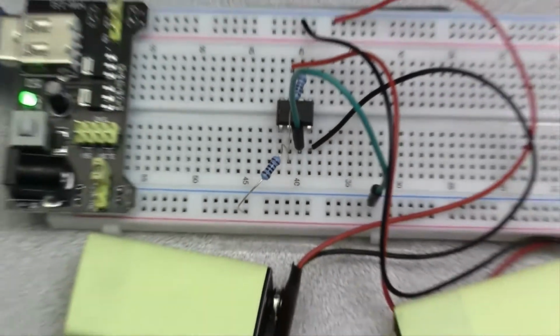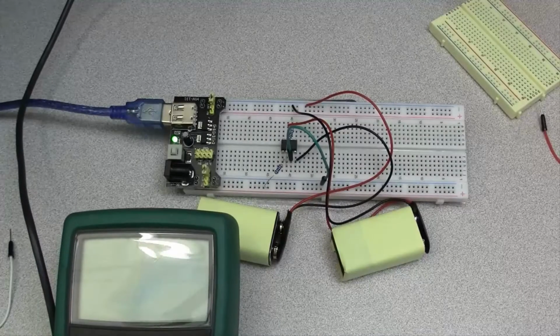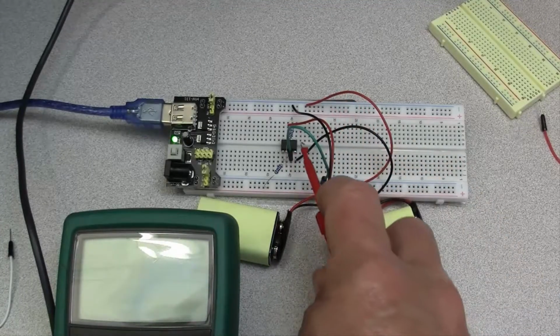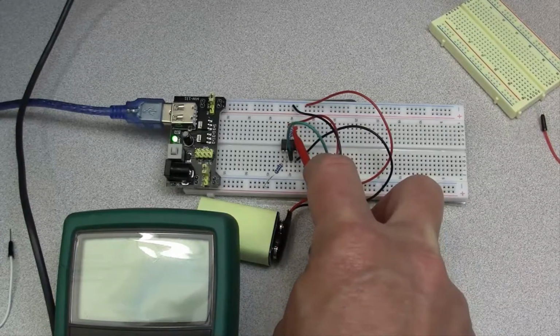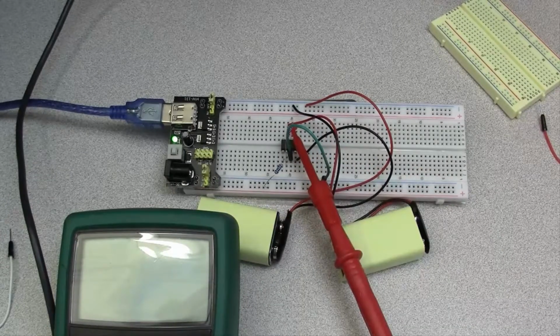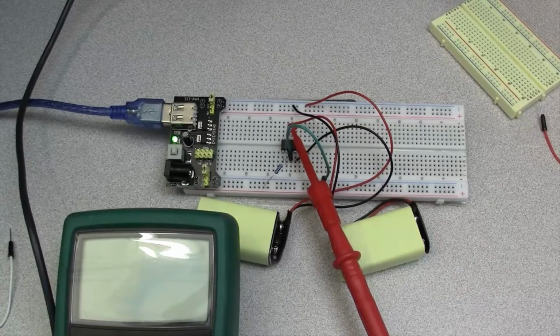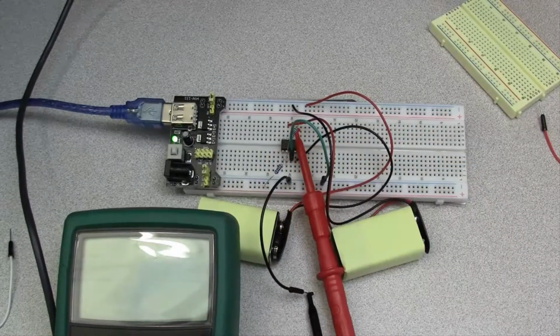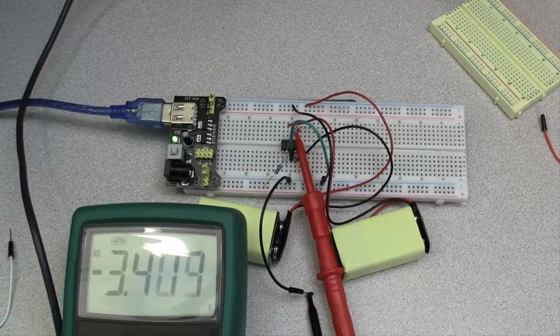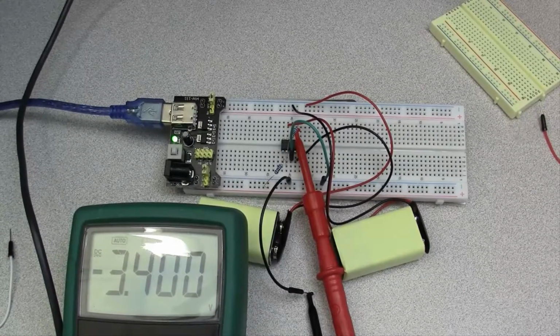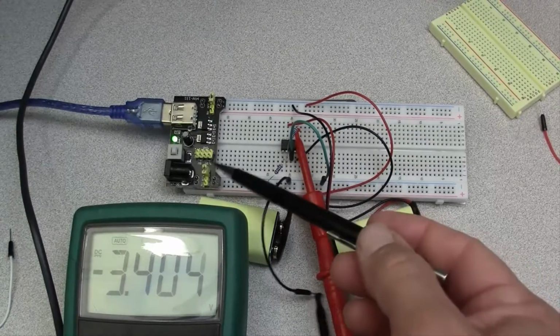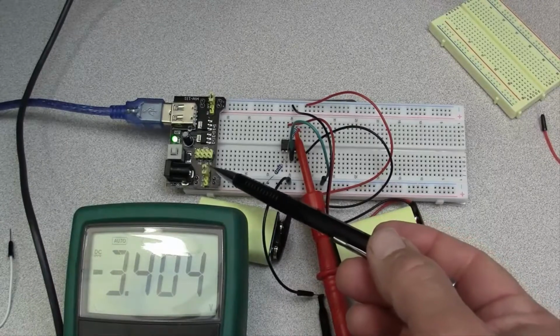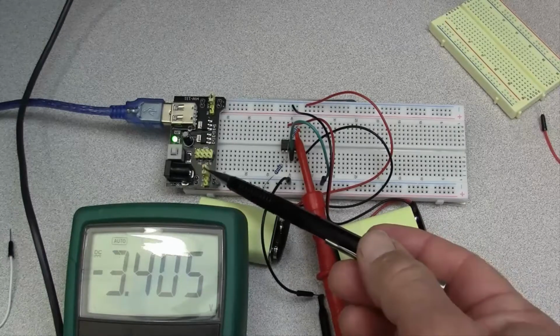Now let's zoom out so I can see my DMM. To measure the output voltage, I'm measuring the voltage between the output terminal at this terminal of the feedback resistor relative to ground, which is any of the blue stripes on the breadboard. Turning on my DMM, I get about negative 3.4 volts, which is almost exactly the opposite of what I would expect from my input voltage, which is a positive 3.3 volts. To get a better idea of whether this is accurate or not, I should probably measure the input voltage.